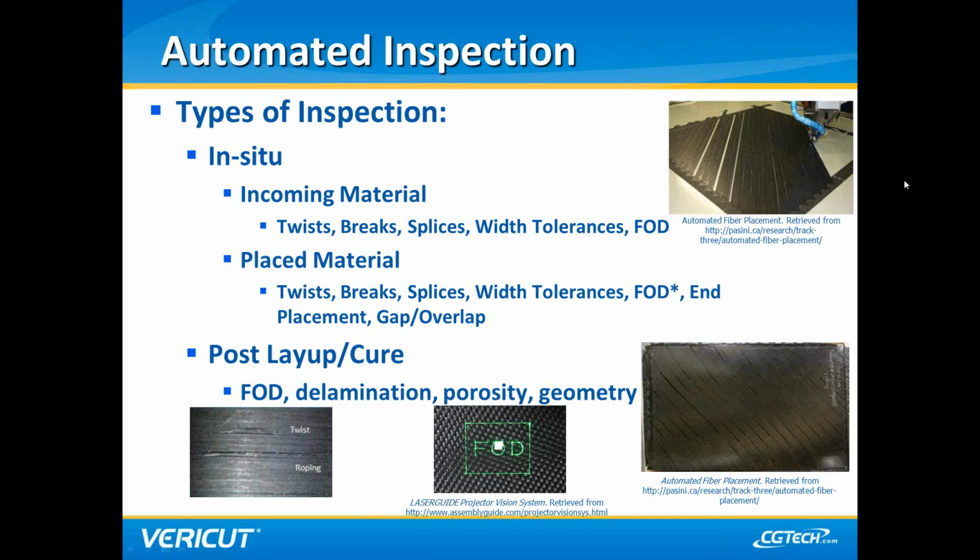I mentioned FOD here because you do have a bit of a challenge when you are inspecting the laid material to look for FOD underneath the part. You could look at the thickness of the material, and if there's an abrupt change in thickness, you may assume that's FOD, but you have a much more difficult time finding that after you lay over the top of it.